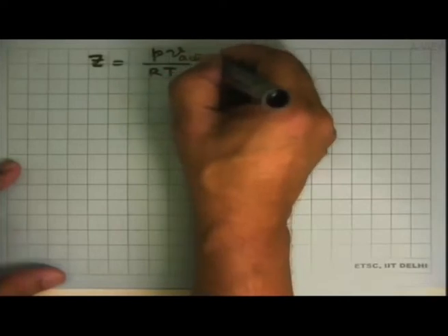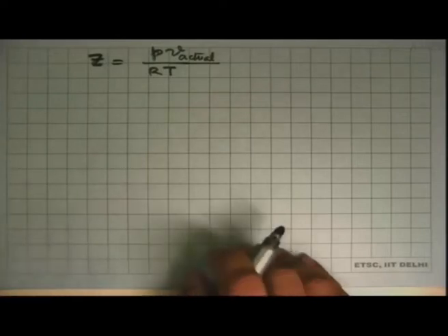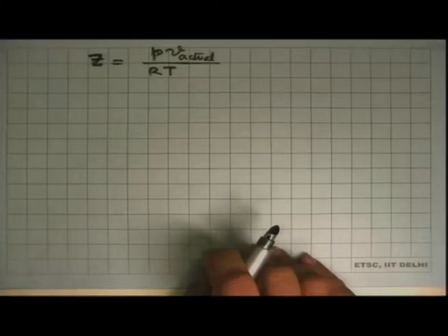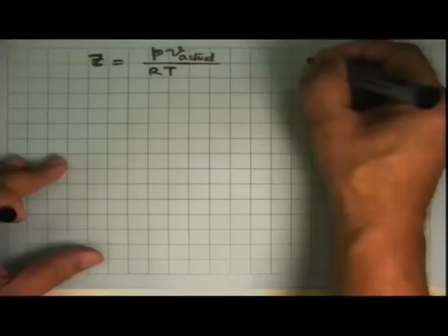But now we should be clear that the V that we are getting is V actual. That means your medical oxygen cylinder at home, it has got a certain specific volume. We know the pressure and temperature at which it exists. So the actual specific volume we know because the mass and the volume of the cylinder were known.